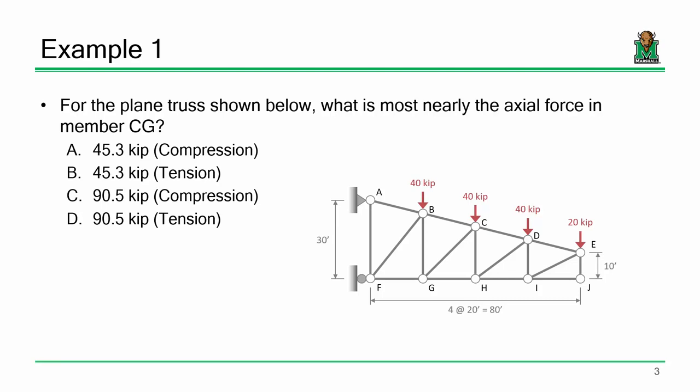That's it. Okay, so that's one thing I want you to take away from this session. This is a nasty truss. All the members are at different slope ratios and whatnot, but now looking at it, it's just cut a section, some moments, and you're done. Okay, so I want you to think in those terms, going with that strategy. All right? Everybody good? I'll tell you what, let's do that. Let's cut a section and take some moments. Let's see what happens.